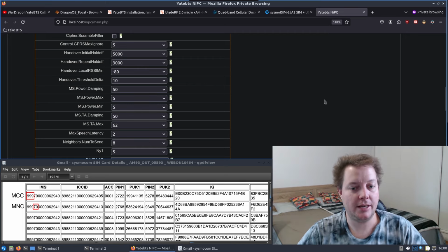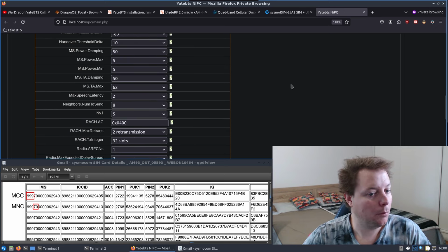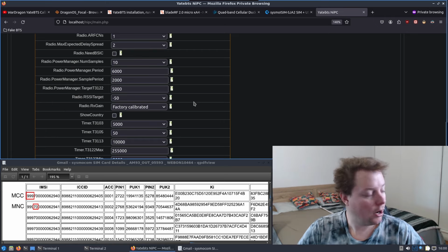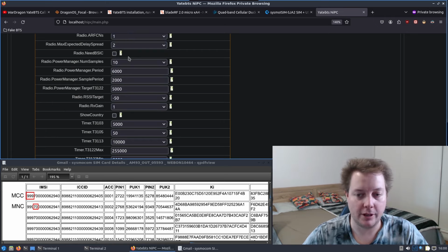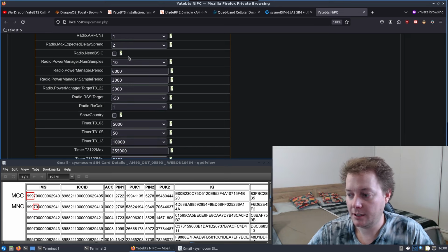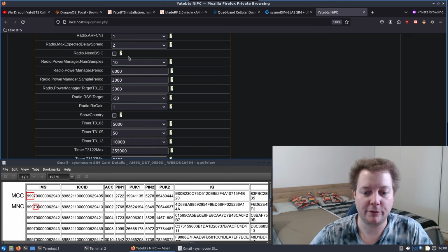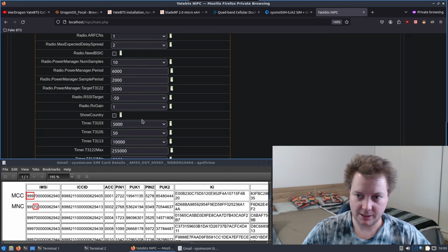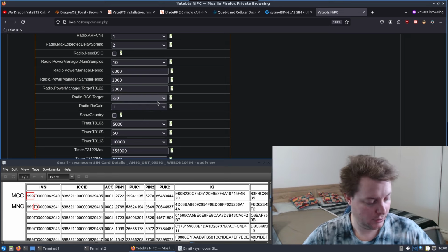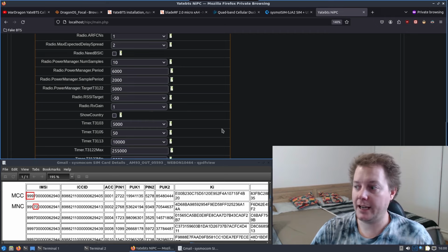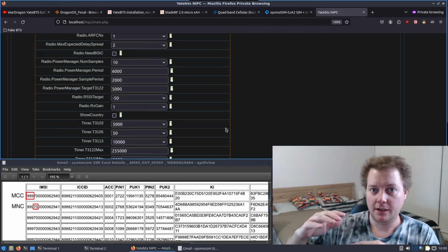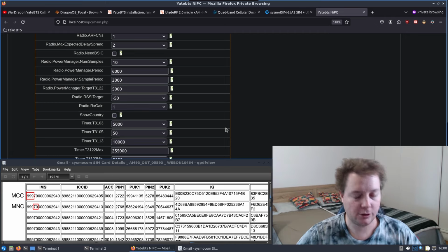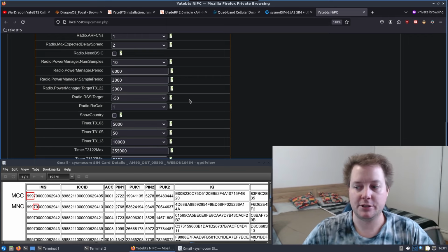And after we've changed that, we need to again scroll down and find the field that says radio RX gain. So I'm going to change this to 1. The reason I do that is because, again, we're conducting tabletop experiments inside a lab environment where the SDR and the phone are going to be in very, very close range to each other. So there's no reason for the receiving gain to be cranked up on my BladeRF. Receiving gain is like the level of sensitivity the BladeRF's receiver will have when listening for the mobile phone signal. So with close proximity, there's no reason to have these values set really high.